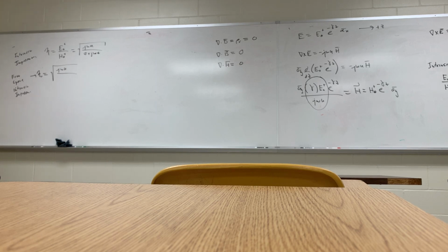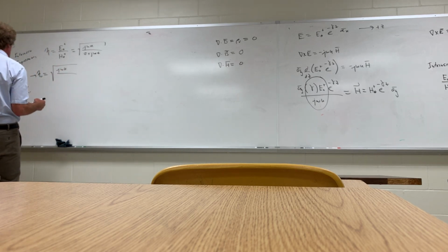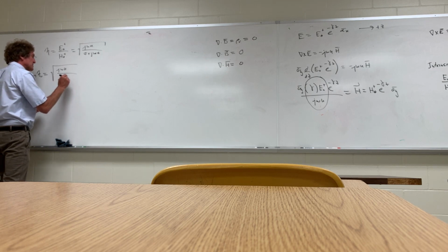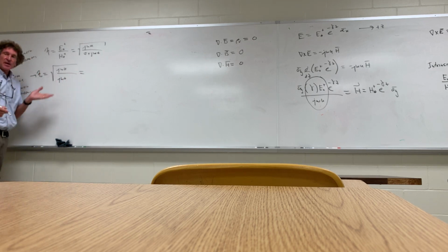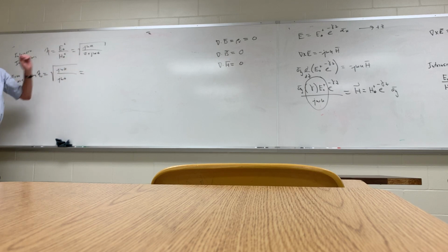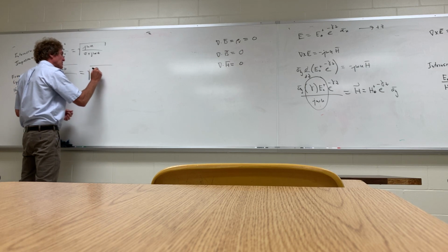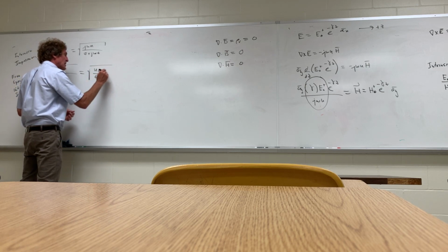It's really just a simple fact. So if it's free space or a vacuum, it's assumed to be 0, and that would be divided by J omega epsilon, right? Now you all see the J omegas are canceled. In other words, sigma will not exist in a vacuum or in free space. And that means it's simply square root of mu naught over epsilon naught.